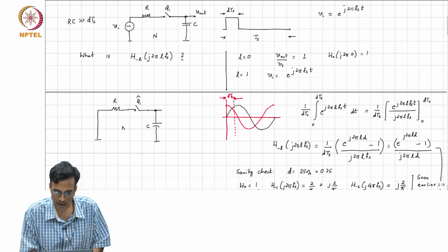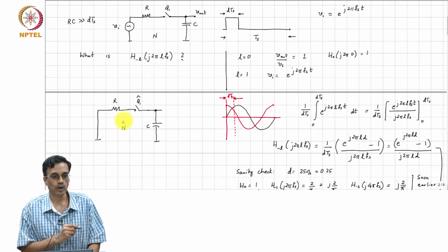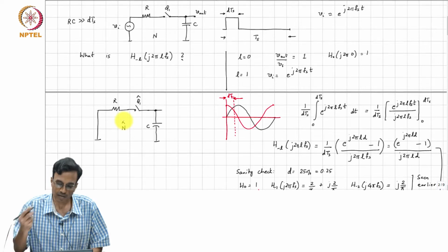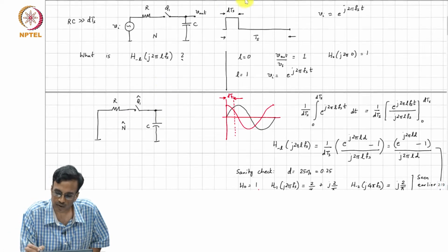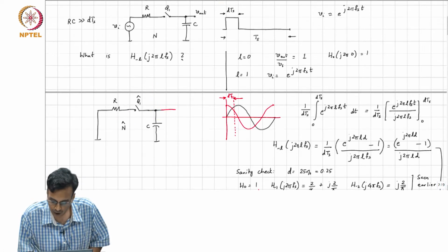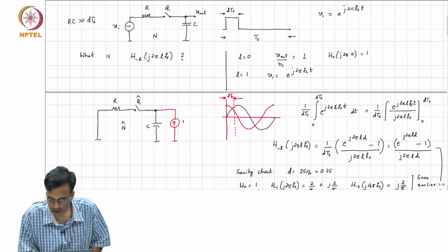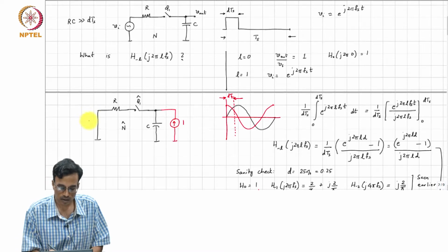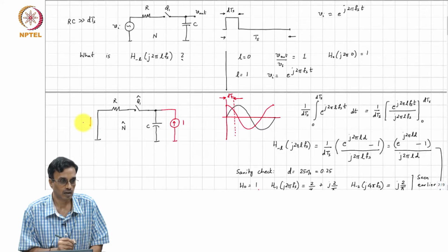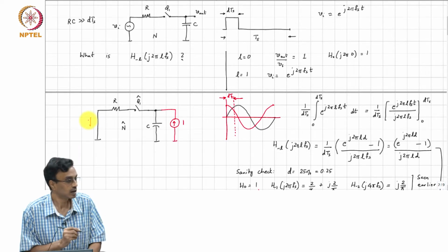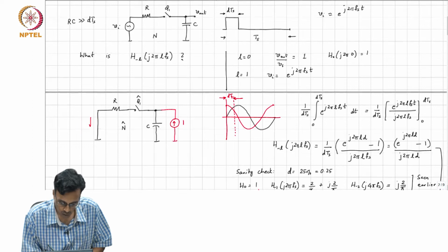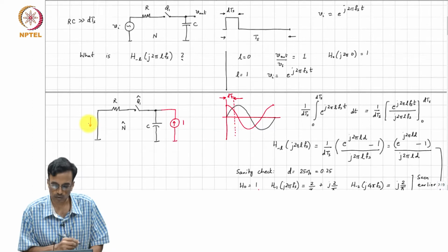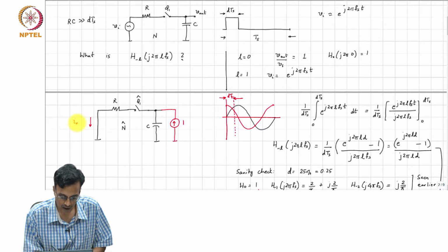So, this is N hat. What should we do as far as the adjoint is concerned? We have to apply a current, and at what frequency? Like DC current. You have to apply a DC current of say 1 ampere, right, and what are we going to measure? We have to find all the harmonics. Of what? Like current only. Current where? That, through R. Through R, through the voltage source, which is the same as that through R, right. So, this is I out.